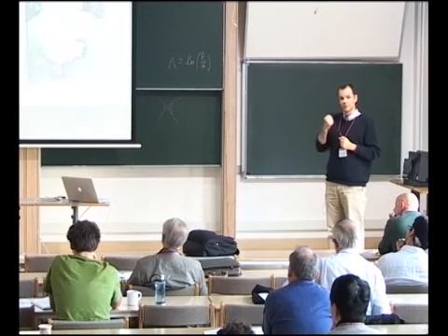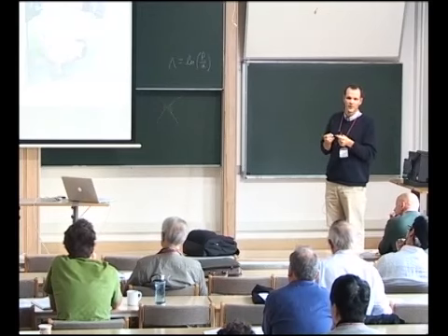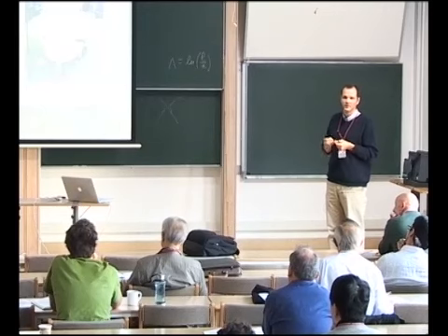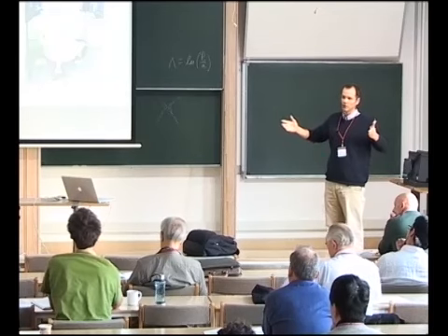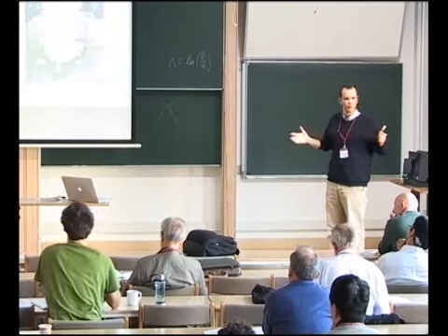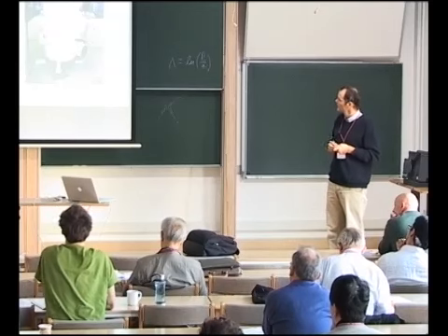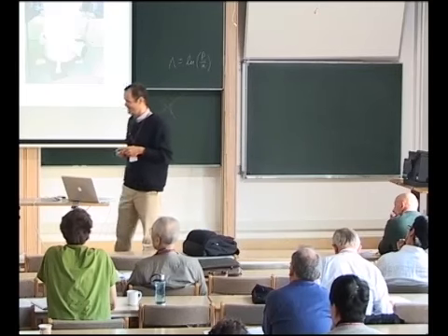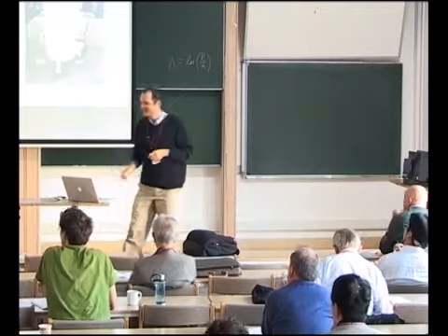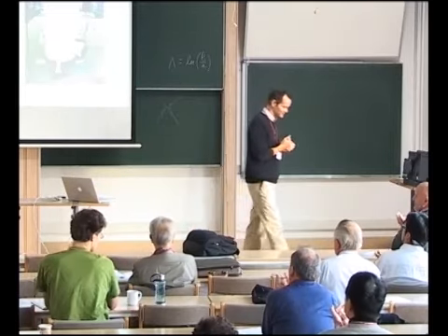So this is going to produce very large Reynolds number, but more important, it's going to have large scales. And this is very convenient if you want to measure fluctuation, because probes are never very small. If you make a probe which is 0.1 millimeter, you are happy. So if a large scale is 10 centimeters, that gives you a lot of inertial range.